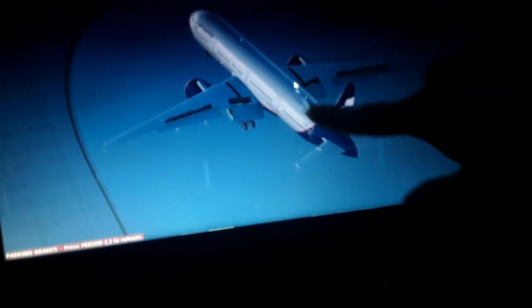So I'll show you now the outside view and talk with you a little bit about this, and then come inside. So you can see here we have the aircraft and the view of the aircraft. You can see the wings of the aircraft that hold the weight of the aircraft in total, and also the thrust from the engines moves the aircraft forward. You can see we have this axis, the wingtip to wingtip, the lateral. We have this, the longitudinal axis, and we have the vertical axis through the center of gravity.